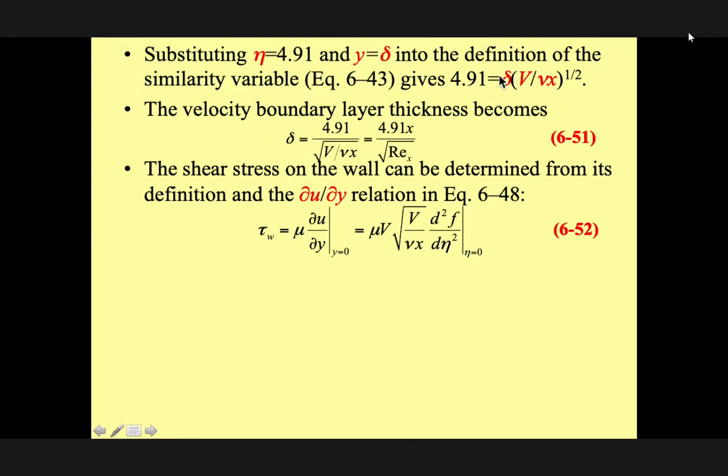And the thickness of the boundary layer can be defined at this one. Look at here, it is 4.9, thickness, velocity, viscosity, and so on. Therefore, when we change it to this form, the thickness is 4.9 times this Reynolds number. Again, look at here, it shows the thickness that is changing as a function of length of the plate.